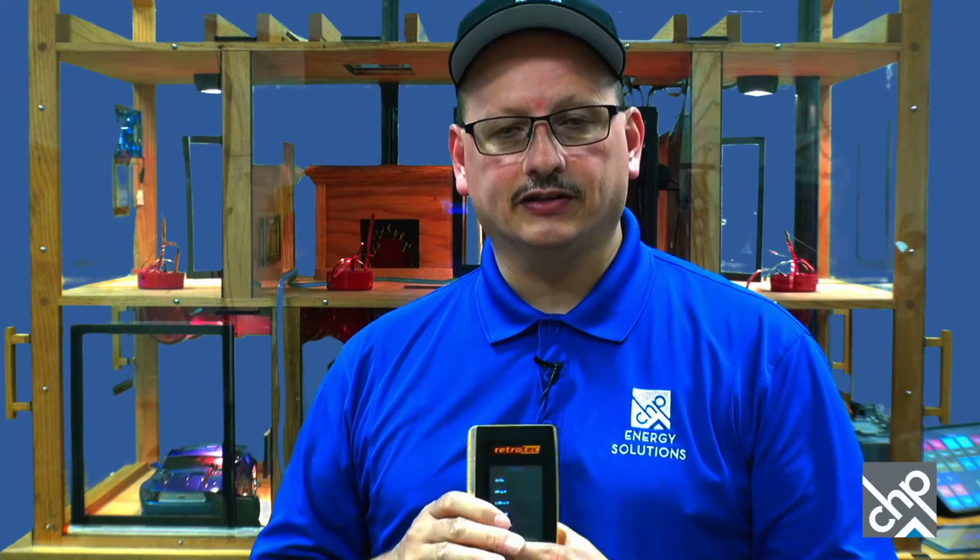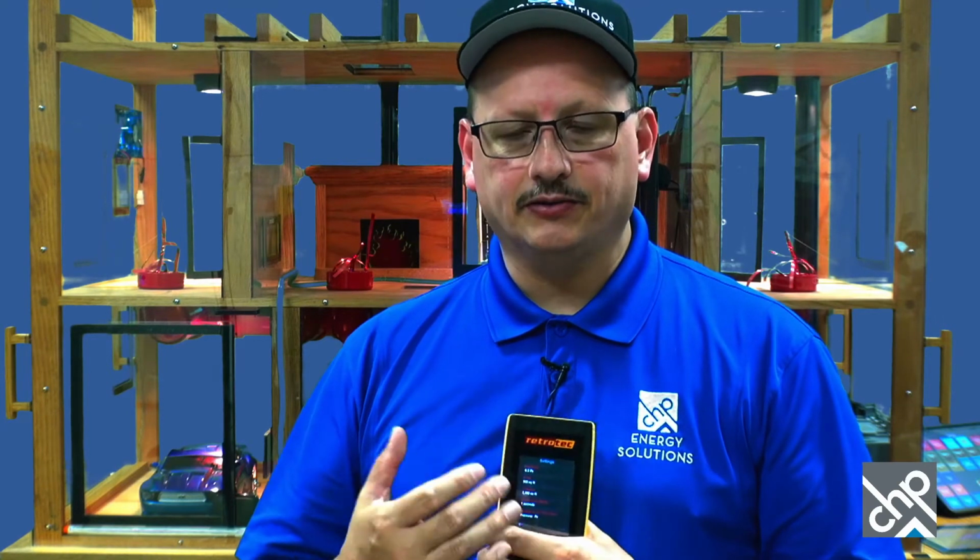So if it was at -2 for your baseline, and then you zeroed that out, then it would just show 0. Versus having to say, well, the initial pressure was -2, I turned on the fans, now it goes to -4. I have to take -2 from -4, so okay, the pressure change is only -2. Whereas doing the baseline function sets that to 0, so that when you turn things on, you're going from 0 to -2 instead of having to do that math. So it does the math for you, which is pretty cool.